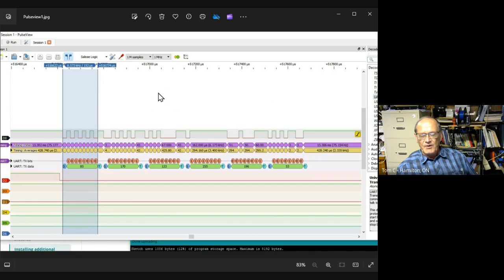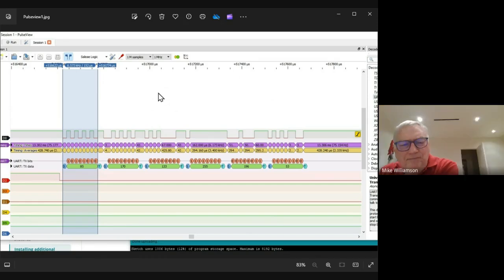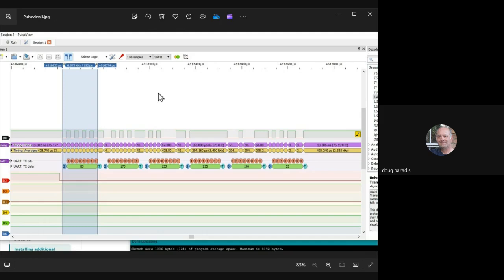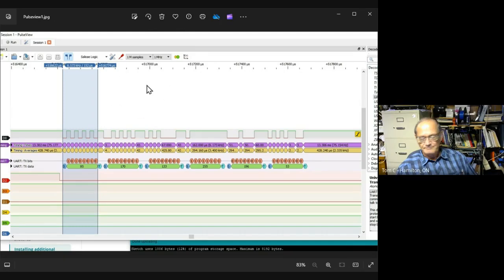Okay. Anyway, this is PulseView. This happens to be showing the 6-character data stream coming out of the little 8-bit ATtiny I'm using to do the conversion. And what you're looking at is the timing decoder and the UART decoder. Some of its functions are turned on, some are not. It's really, really good. It's every bit as good as the Saleae product for what I'm doing here. They would do that too, though. So they're about the same. Yep. And this one's legitimately free.